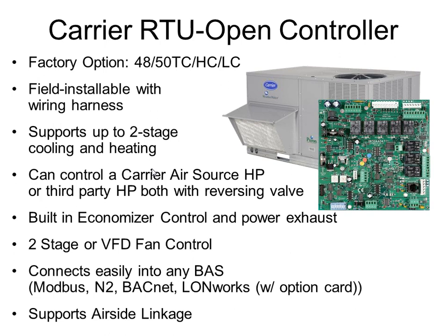So just real quick on what Carrier can offer for its DDC VVT system. We have a standard application controller called the RTU-Open controller. You can get these factory installed in any Carrier rooftop unit, or you can field install them in any rooftop unit. The controller runs through the thermostat terminal of the rooftop, so it calls for heating and cooling and fan the same way a regular thermostat does, but this has all of the VVT logic built into it, pre-programmed. It just needs to be configured.